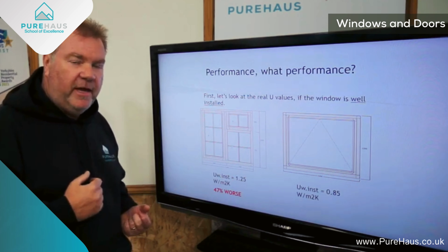You've got one window in a house, that is almost negligible, believe it or not. But you've got 10 windows, it's 10 times that. So always look at your U values and your actual design.